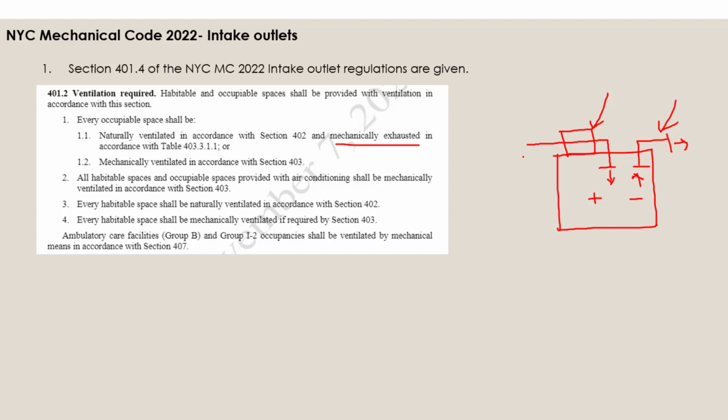So in the positive pressure case, you're pumping air into the space. And in the exhaust, as the air is leaving the space, that air has to be made up with an equivalent amount from the outside. So it's actually going to be bringing outside air into the building from the exhaust for the same amount of CFM that is being exhausted. And typically the outside air goes into the space through cracks in the windows, in the construction of the building itself, or through doors that may be opened up, or just through the undercuts of the door and the openings that are around the door.